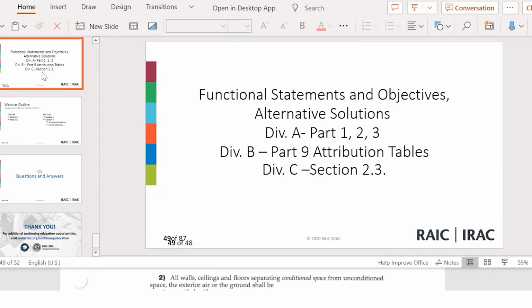And for houses, for energy conservation and energy efficiency, we have the option of using the performance compliance, and there's documentation required with it. It's limited to modeling performance, comparing the reference house to your actual proposed house. Those modeling provisions are allowed for houses and houses with secondary units only.